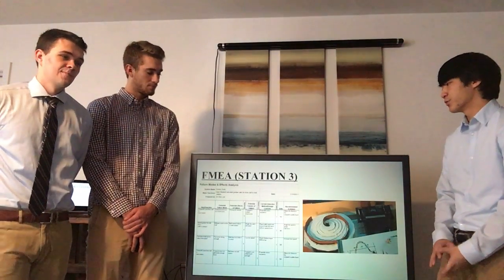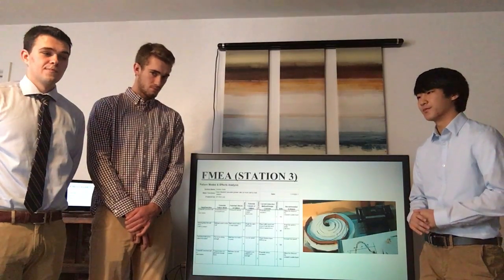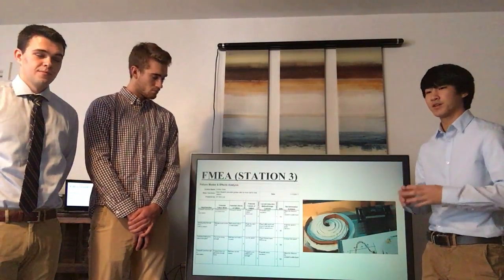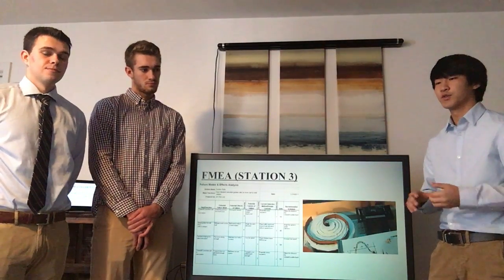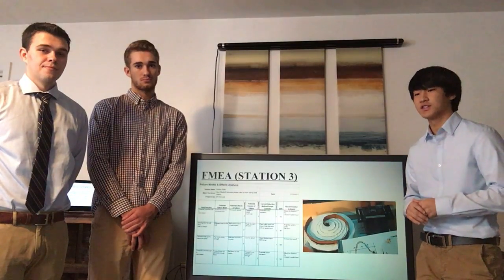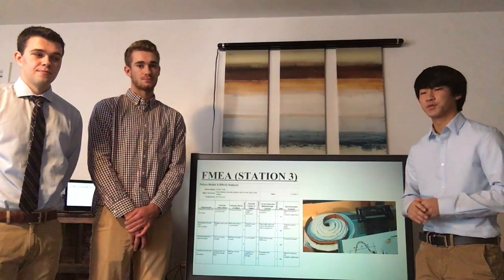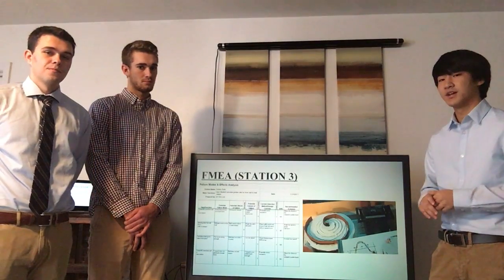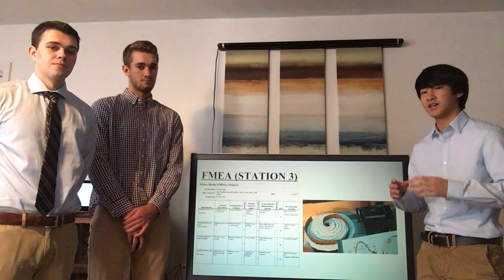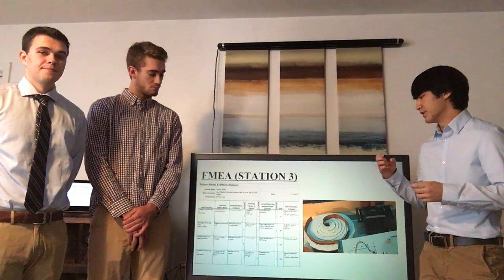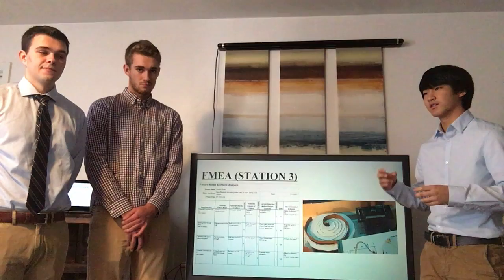So the part of the station which will create the highest risk priority number was the slingshot catapult itself, as if it is not properly aligned, it would either create too much force, which would have the incorrect exit velocity, or it might generate not enough force, which will prevent the ball from reaching the exit of the station. This can be prevented by using projectile motion to properly set the catapult slingshot and the exit of the station in the right places.